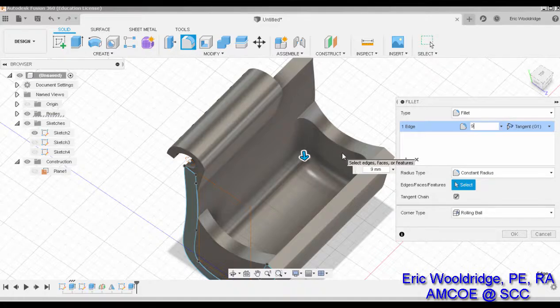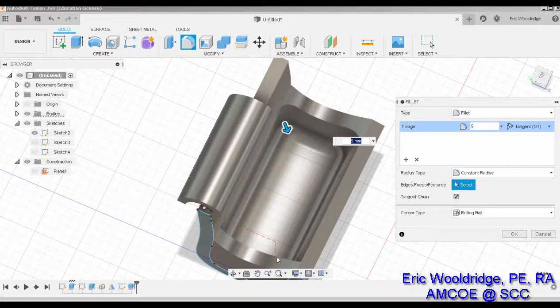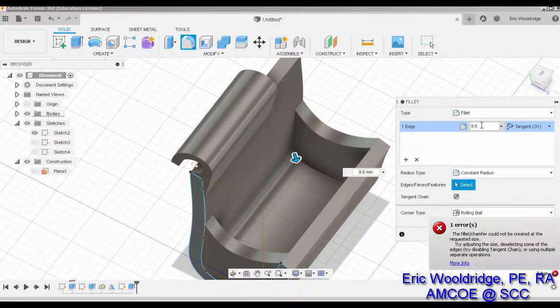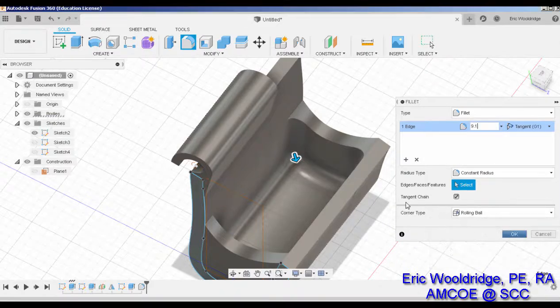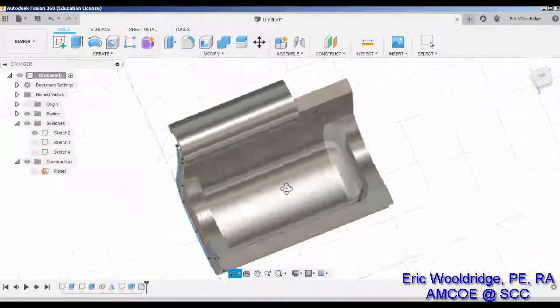I could even turn around and do a little bit more of a unique merging there, because as it prints, I don't want it to build all the support material up just to get to that point. I'd rather eliminate that as much as possible. So let me try like 9.8. No, it's like 9.5. Nope. How about 4? Still not there. 3, 2. Nope. Looks like 9 is going to be it. 9.1. We at least got that much. Okay, so that's got as much of the overhang as I can take care of with the fillet command.